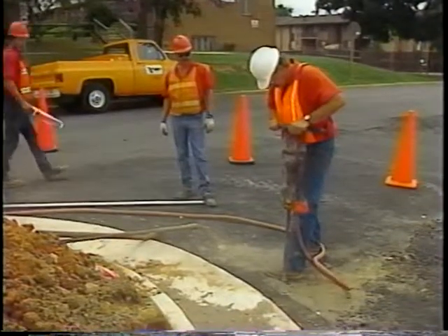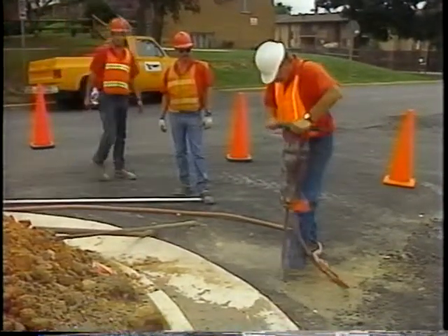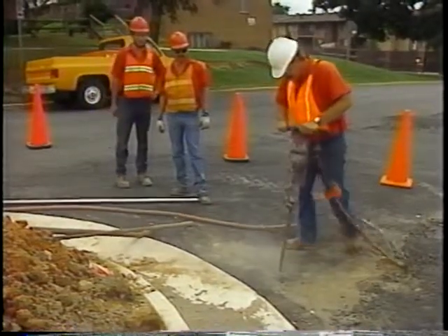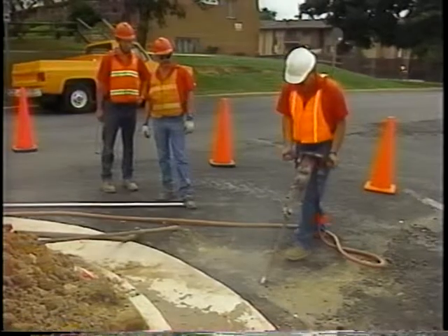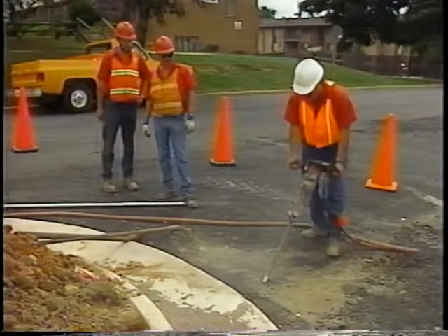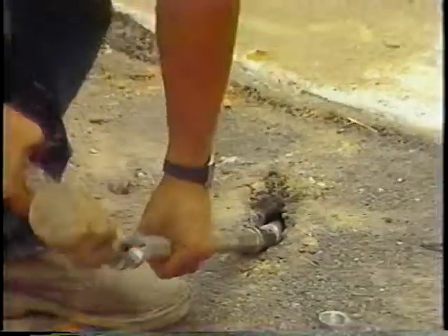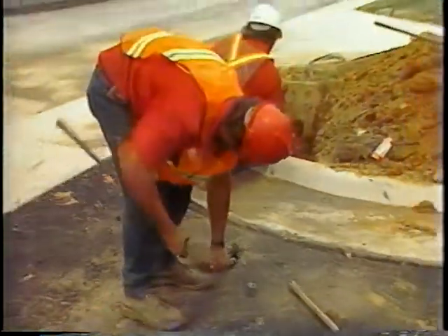At intersections with curbs, the joint where the road surface meets the curb line can cause problems for the twisted wire through horizontal and vertical shifting. Using a jackhammer drill or punch-type tool, make a hole in the curb and install a watertight, flexible conduit.